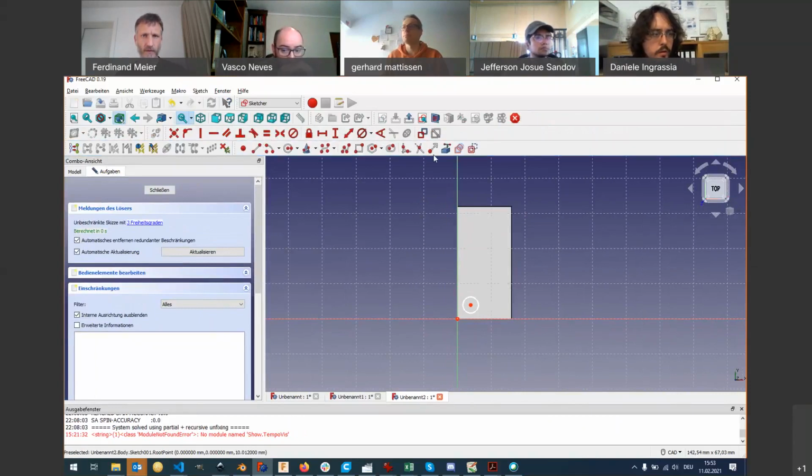And so you should see a symbol that looks like a blue box, pick edges from other geometry. Which I actually kind of like, because it reminds you that you're now creating an external reference to your sketch.